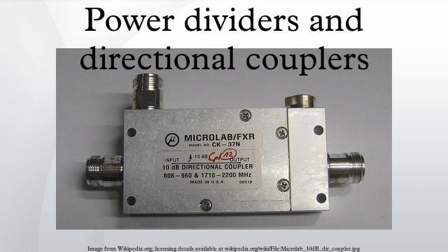However, tightly coupled lines can be produced in air stripline, which also permits manufacture by printed planar technology. In this design, the two lines are printed on opposite sides of the dielectric rather than side by side. The coupling of the two lines across their width is much greater than the coupling when they are edge onto each other. The λ/4 coupled line design is good for coaxial and stripline implementations, but does not work so well in the now popular microstrip format, although designs do exist.